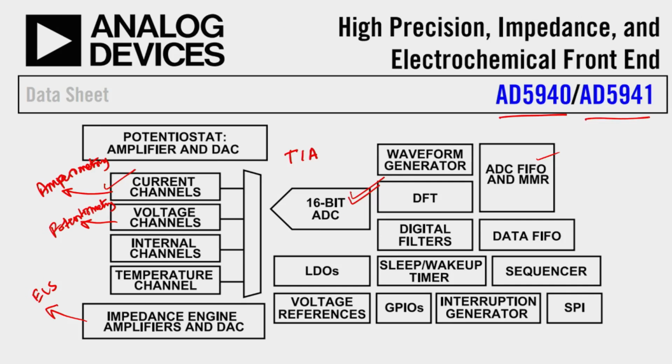So if you are developing wearable sensors and you don't want to do ASIC design, since ASIC design requires in-depth knowledge of electronics, then you can go for AD5940 or AD5941, and this is the evaluation board of the chip. Generally, let's say I want to test, and this requires some programming. If I want to program the chip, test it and use it without having to develop my own PCB, then I can use this AD5941 or AD5940 evaluation board.